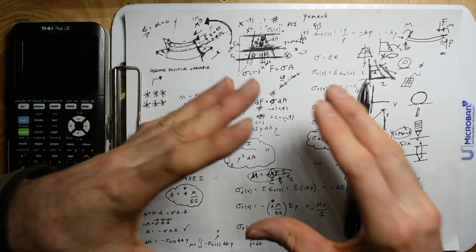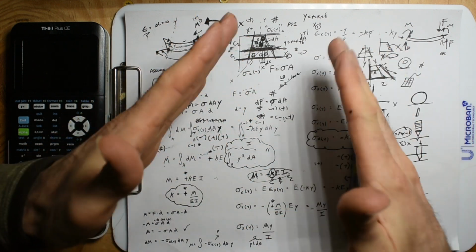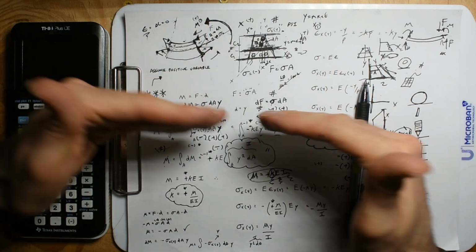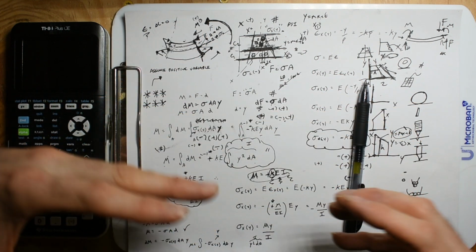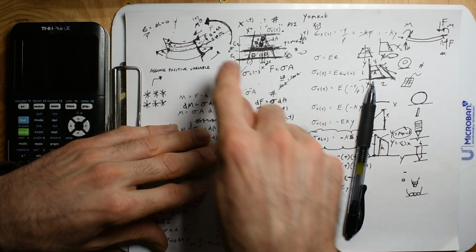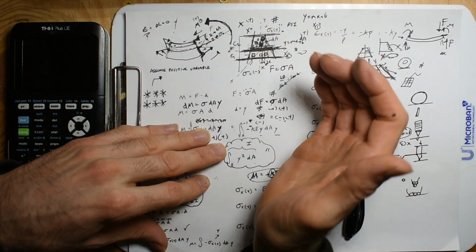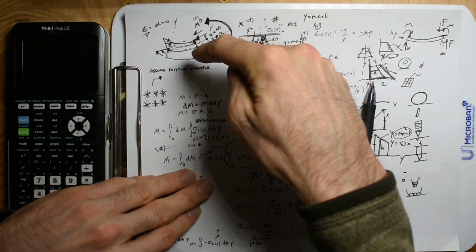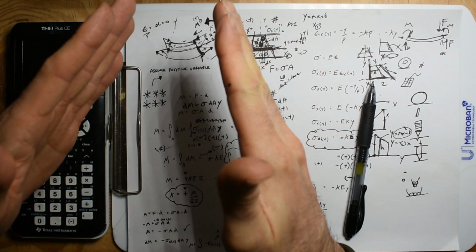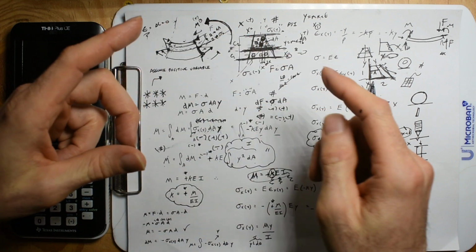If something gets shorter, that means that it's compressing force. The force is compressing those materials. If it's getting longer, force is lengthening. And so if we have a force there and a force there, that's generating a moment. So the moment is generated by the forces. The forces are there because of curvature causing strain.